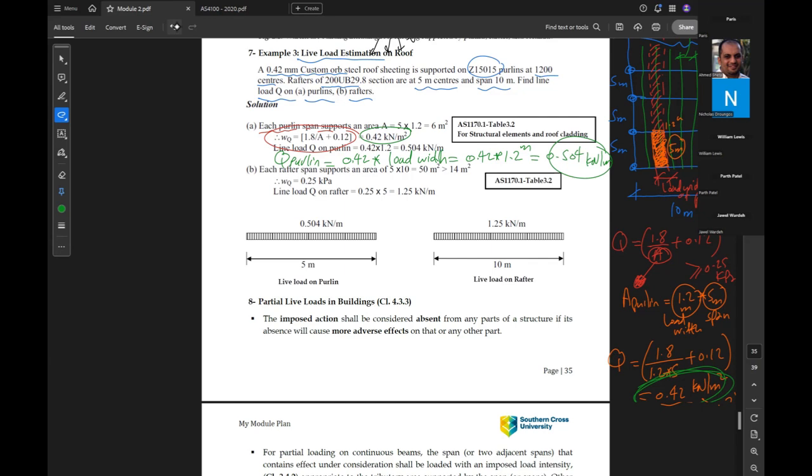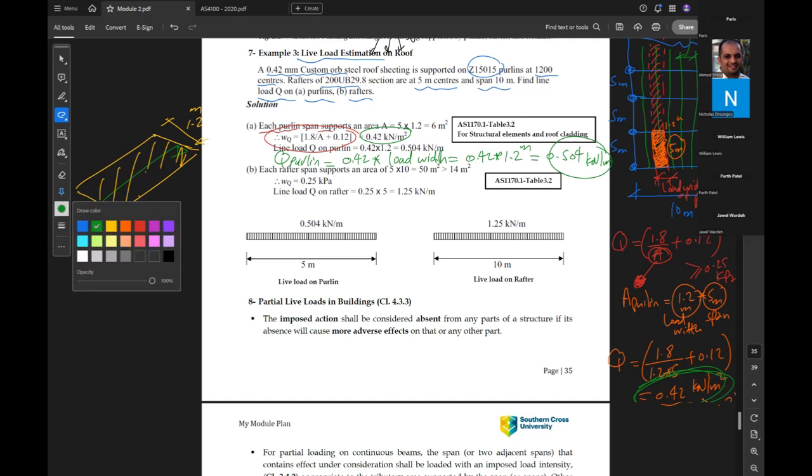So the idea is we have the purlin just in 3D. The purlin is carrying this area, right? How much is this area? The width of this area, how much? 1.2 meter. But we need to convert this yellow area to this blue line as UDL over a line. So how we concentrate this area to this line?